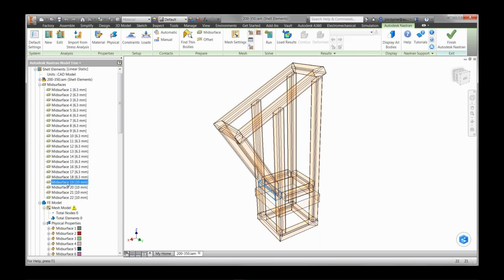into the shell mesh. And as you see, when I'm collapsing into the shell, each of the shells has its own thickness, so you don't have to go ahead and define the thickness for each of the shells, which is a very much automated process. And then comes generating a mesh.